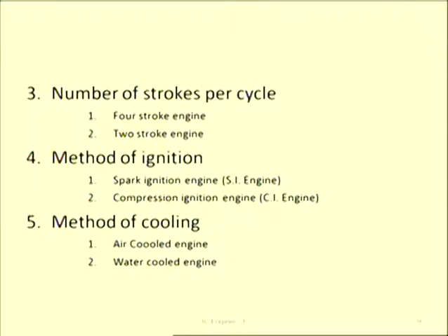The third stroke is expansion. After compression there will be ignition, then the combustion process will take place, and the high pressurized gas will exert pressure onto the piston. So again the piston will move down. The third stroke is called the expansion stroke or power stroke, which is useful. And the fourth stroke is the exhaust stroke, meaning after the expansion or power stroke, the burnt gases, flue gases, should go to the atmosphere. So the exhaust stroke will start and the flue gases will go into the atmosphere.